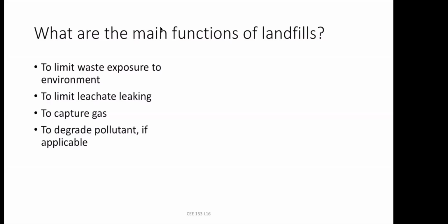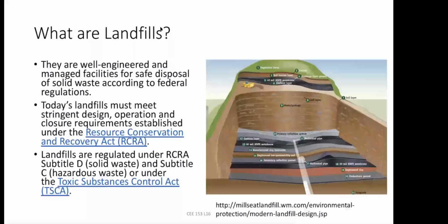So again, the main function of the landfill is to limit exposure of waste to the environment, to limit the leachate so that you don't pollute groundwater, to capture the gas for energy production, and also to degrade some of the pollutants if applicable. This is how the landfill looks. If you see, they are well-engineered landfills. You have different systems. At the very bottom you have a layer system so that it prevents the pollutants or the leachate from getting into groundwater.